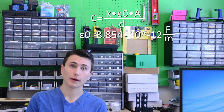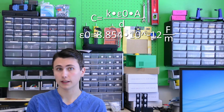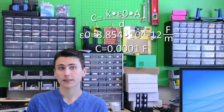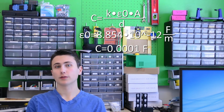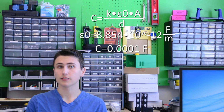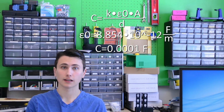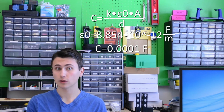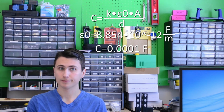In other words, the capacitance value can be read as a decimal place, 3 zeros, and then a 1. The constant in our numerator, the permittivity of free space, is 8.85 picofarads per meter. This is approximately 9 times 10 to the negative 12th, or a decimal point, 11 zeros, and a 9.